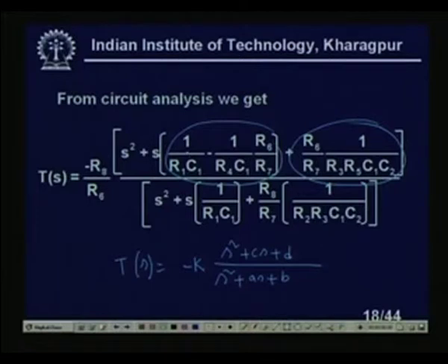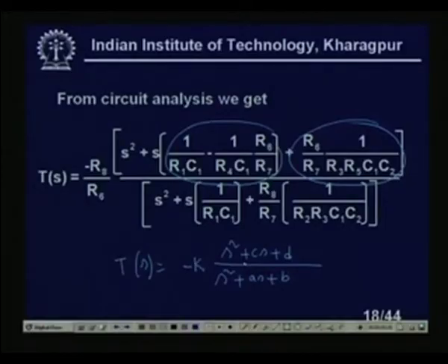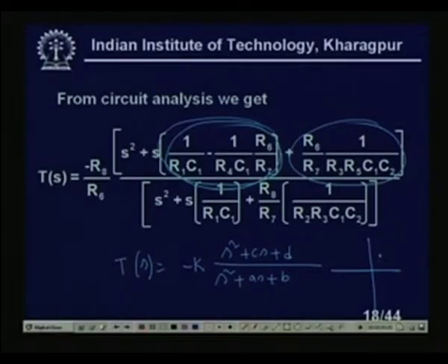Only problem, if you look at the numerator, you see that here we have a subtractive term as a coefficient of S. The problem with this subtractive term is that we are making this coefficient 0 by signal subtraction, right. So, if this coefficient is not exactly 0, then even though I try to realize the low pass structure, where as you know the pole zero pattern has 2 complex conjugate poles and no zeros, we will find that it is not exactly the same pole zero pattern, right. So, these are the only difficulties in this type of state variable structure, otherwise it is a tremendous advantage.